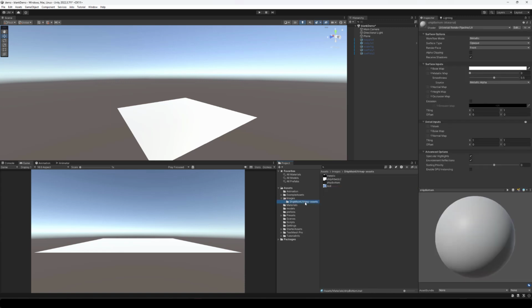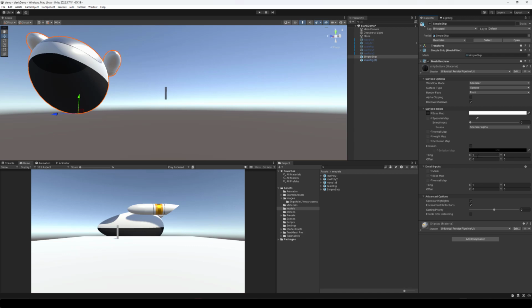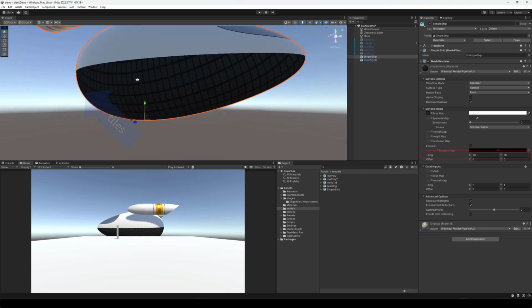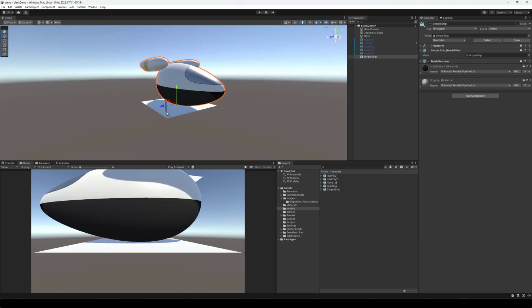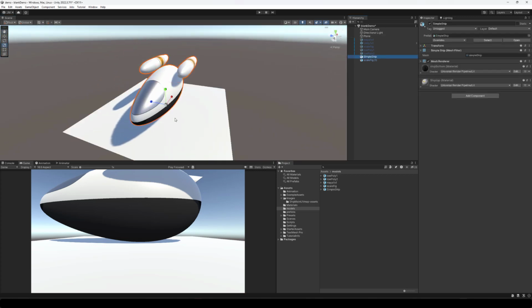And a third image is used as a tile for the bottom, and we're going to repeat that to create a tiled look. It's a separate material, so it's easy to tile this with some larger number to create the look you want. This is a super simple example, but demonstrates how you can custom make images and use them to define materials in Unity.